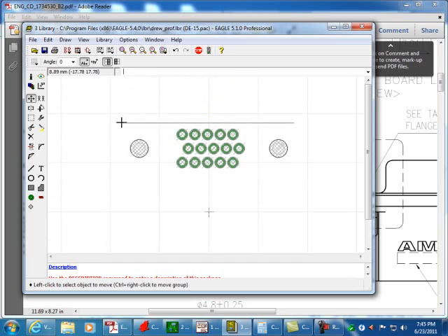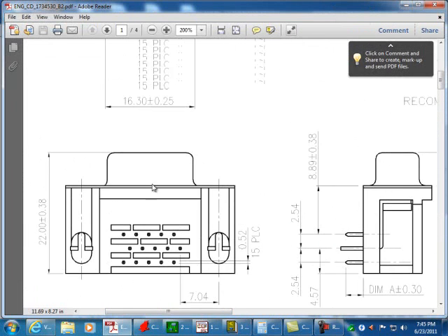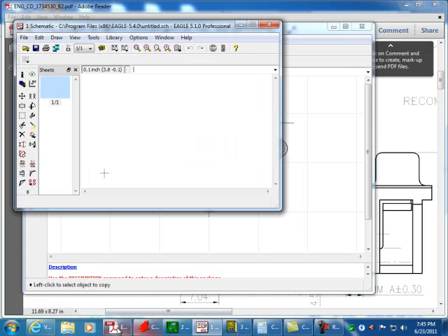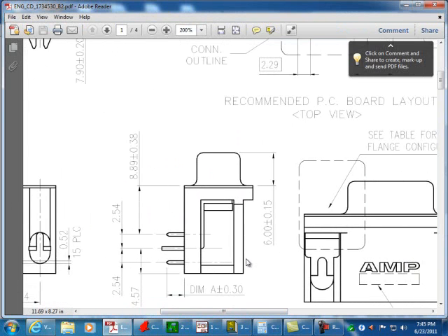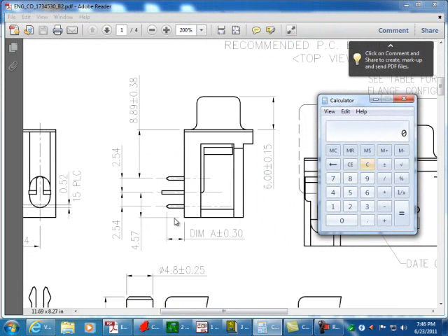And we know that this is the same length because it's a box shape up until the actual connector itself. It's all box shape. So I could just copy that. I can't copy that yet. Actually, we need to figure out in total how long the whole connector is. And that's probably something worth writing down. So from this edge to the middle pin is 4.57.